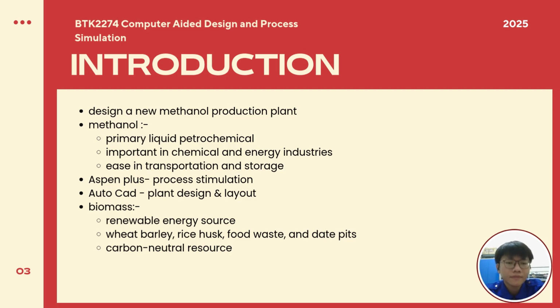We model it using the Peng-Robinson equation of state, with all chemicals and reactions also assumed to be at equilibrium. The combustion and gasification blocks are modeled as isothermal, which means there's no pressure and temperature difference throughout the process, and all unit operations are treated as zero-dimensional, meaning they have uniform temperature and perfect mixing.